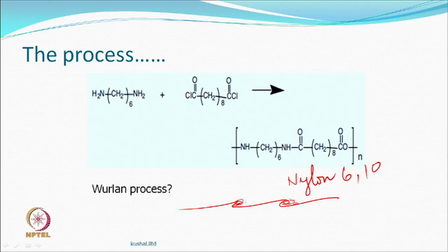Your aim is that if something goes here, then the friction in this direction and the friction in this direction would be more or less similar. So, that directional frictional effect which is responsible for the movement and the felting will be taken care of to some extent. There are other polymers also available. So, polymer coating is one of the ways in which you make shrink resistant wool. So, that is the possible solution.